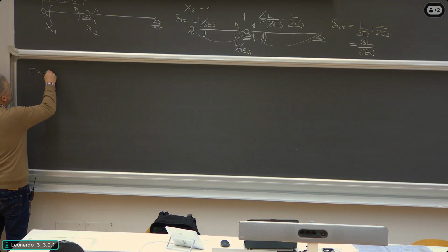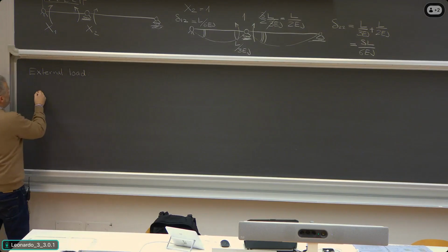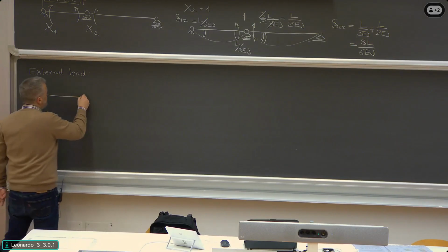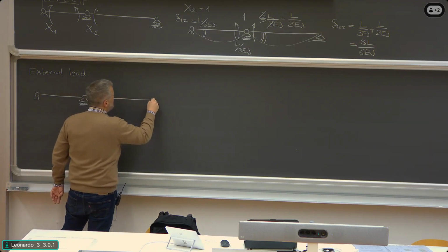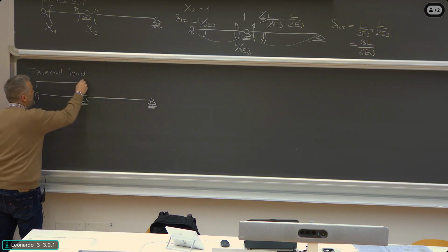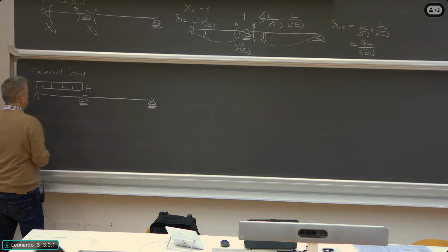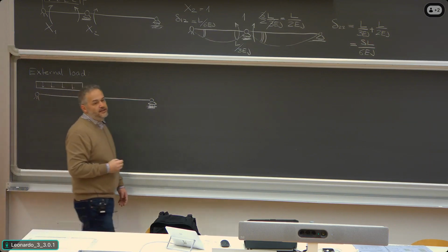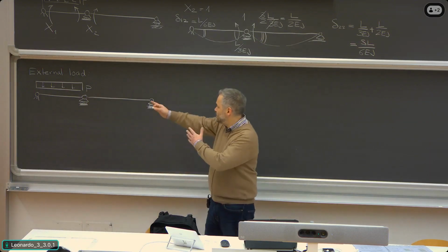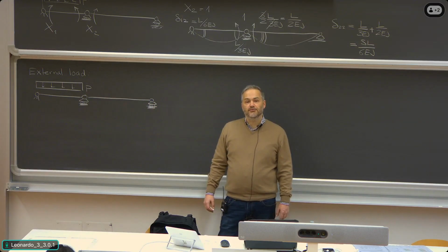Now the external load does not have to be changed in terms of value, no unit value, we can use it as it is. So again, the structure, which is deprived of its continuity with the ground to the left and at point B, and we apply a load which is P, distributed load. So the deformed shape is exactly the one you find at the back of the page or in manuals. Standard case of simply supported beam with a distributed load.